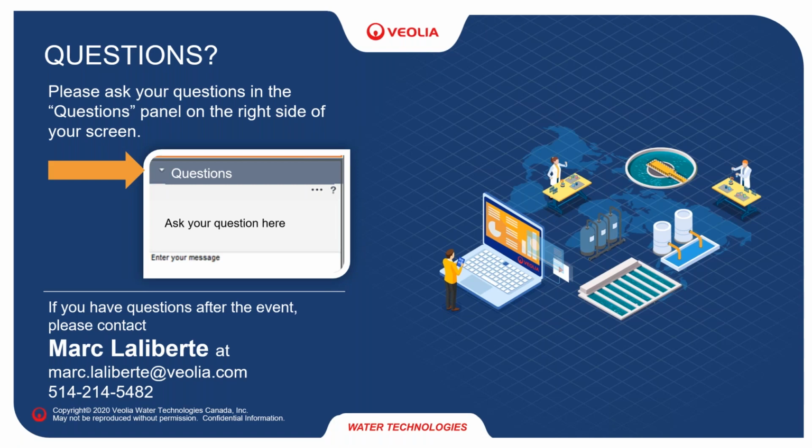Where it does require readjusting is if there is a qualitative change in the water quality. So you are not used to seeing, I don't know, nickel in the water, and then suddenly you've got a new source of water coming in, and that source is very rich in nickel. I may have to tweak my pH and my coagulant dosage and maybe go with sulfide precipitation. I don't know how to do that. So that is more of a challenge.